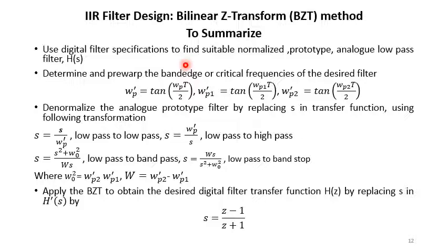The second step is to determine and pre-warp the band edge or critical frequencies.